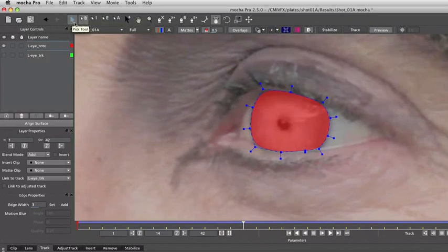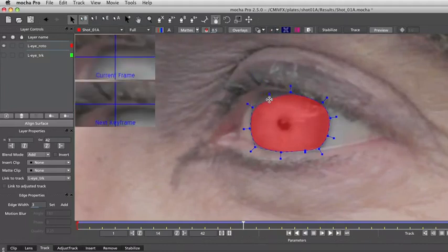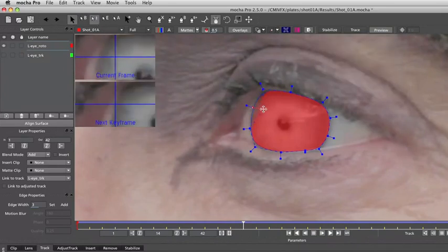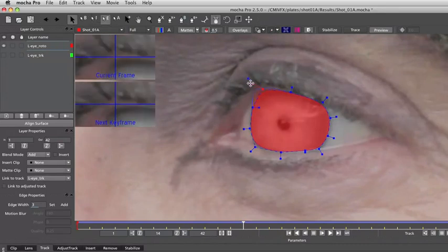The pick tool by default uses this first icon that moves both the inner and edge points at the same time. So when you drag a point, you are moving both controls at the same time. This second icon will move only the inner point, creating a feathering effect. The inner points should be moved inside the mask. Okay, I will hit undo and move to the edge point tool. Move the edge points outside the mask to create the feathering effect.